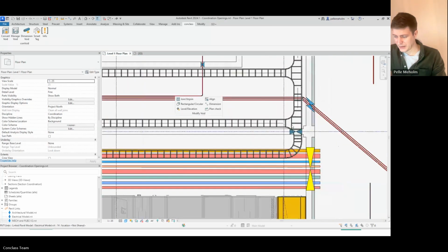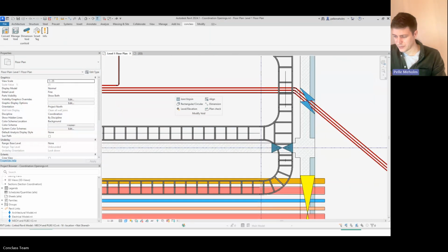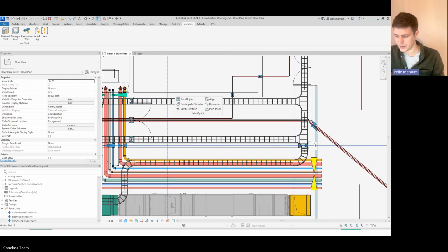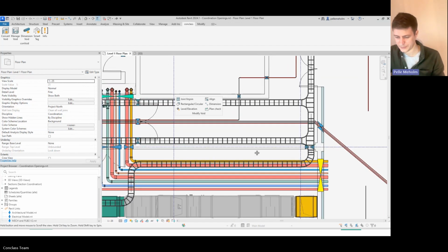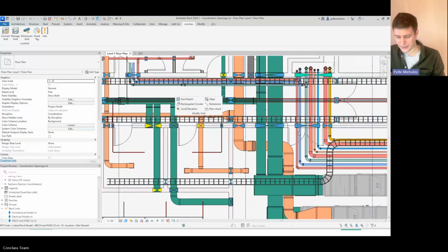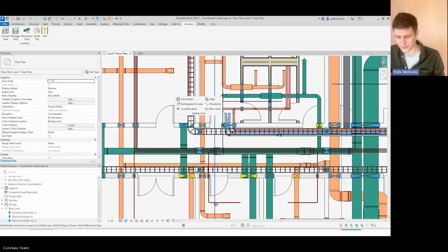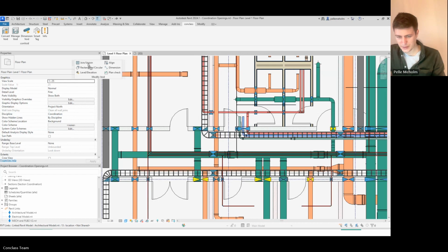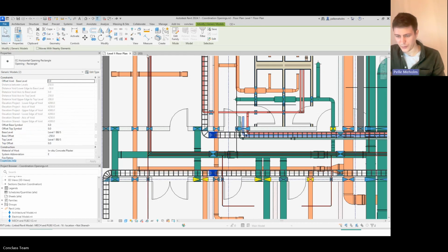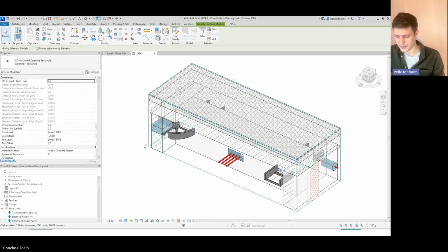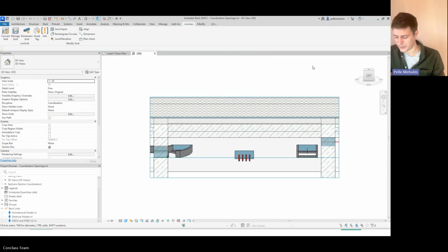Great. As you can see here, ConVoid will also create openings with a slope. You can also disable this behavior to create straight openings. But so far, everything looks good, meaning now I want to focus on the oversizes of the openings, especially for the cable trays.